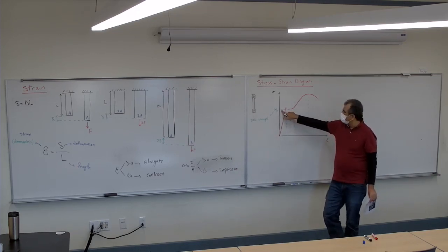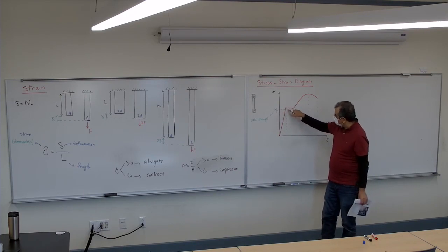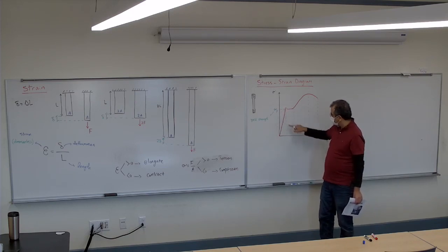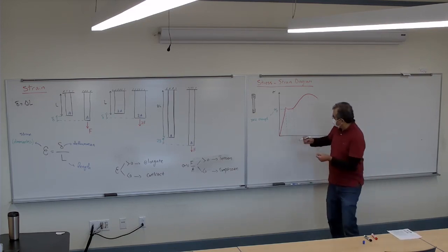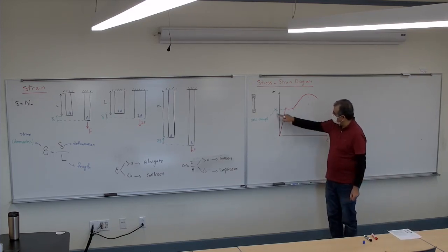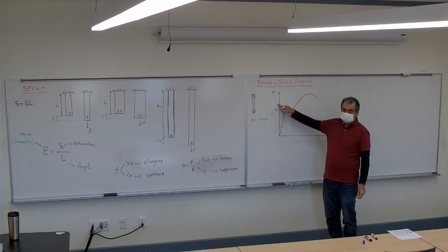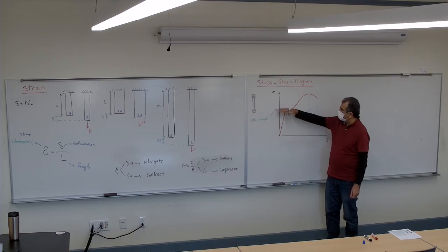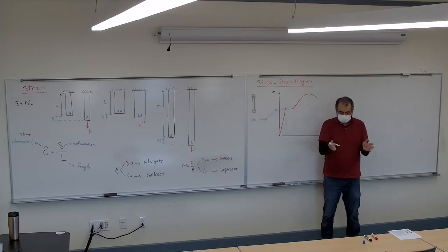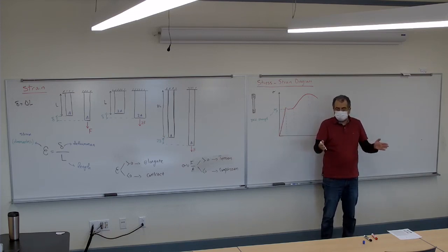Okay? Forget about that little tip there. When I get to that point, if I start to stretch it further, the force doesn't increase. The force stays there. Basically I increase the force, increase the force, and when I reach that point, without further increasing the force, it just keeps deforming.